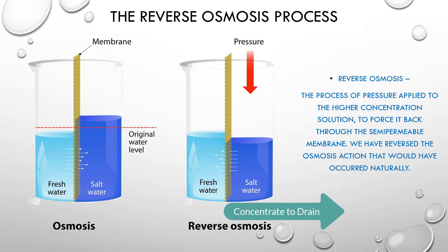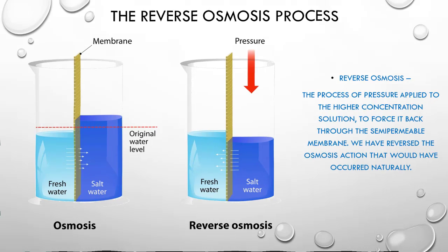The pore size of the membrane determines how small of a particle or water ion is allowed to pass through to what we would use as our treated water. This is why reverse osmosis, as I said earlier, will always have a small amount of dissolved ions in the produced water that is correctly called, by the way, permeate. The drain or wasted water is correctly called concentrate.